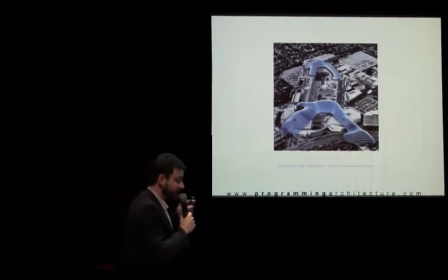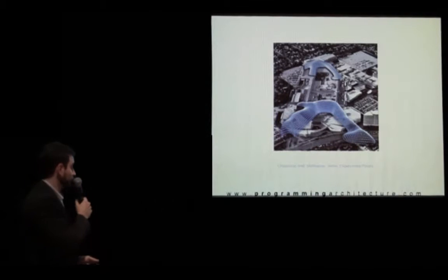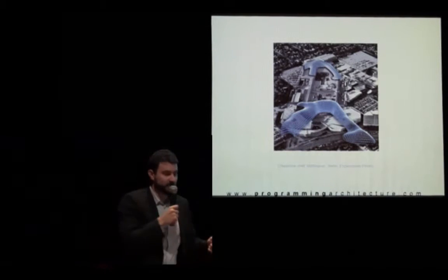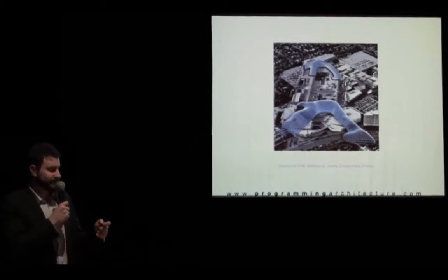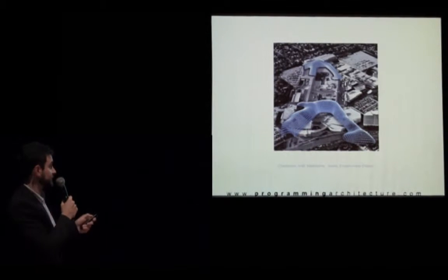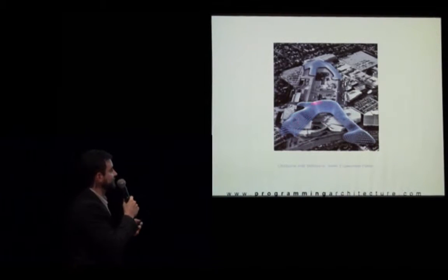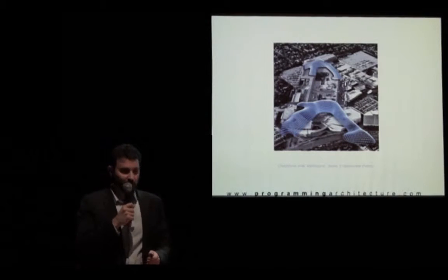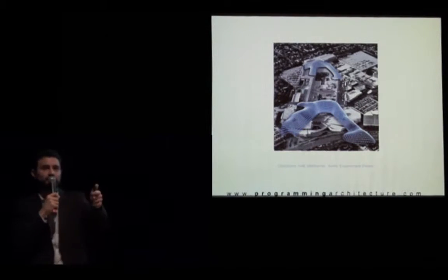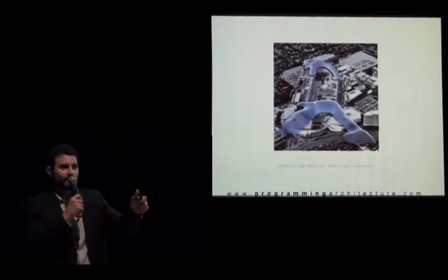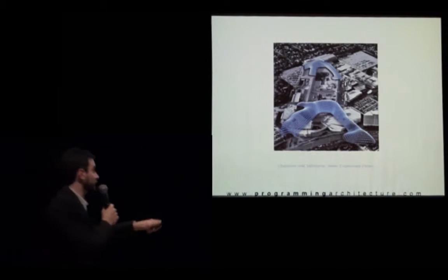I also use static analysis in a very innovative way in the Chadstone Mall in Melbourne. It's a project being done right now. And just so you know, engineers usually, when they do static analysis for glass, this is what the main subject was here. It was the 3,000 glass surfaces that cover this grid shell roof. They estimate which is the worst case. Which glass is the worst, and they do the static analysis for that, or maybe for 2 or 3 more, and that's it, they extrapolate.